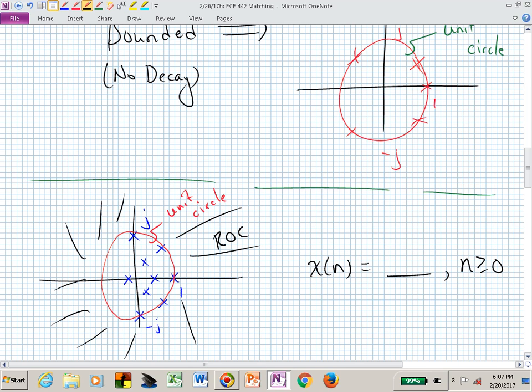This one pole at 1 will give you a constant behavior, and the others that are somewhere else on the unit circle, they're going to be shaking with a sinusoidal behavior. Depending on what? Depending on their angle relative to the real axis. That governs their sort of frequency of oscillation. Does that answer your question? So now I forgot the question, but I answered it apparently.